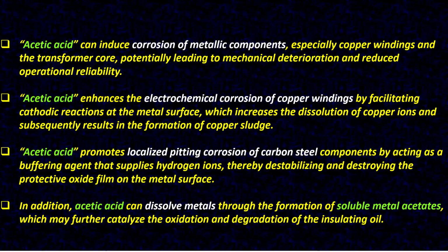In addition, acetic acid can dissolve metals through the formation of soluble metal acetates, which may further catalyze the oxidation and degradation of the insulating oil.